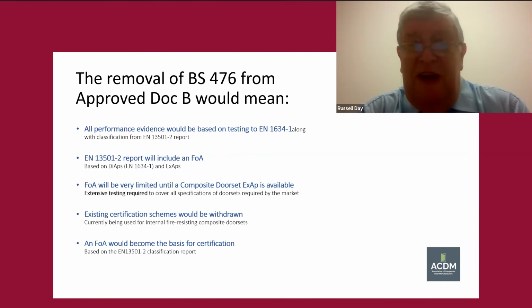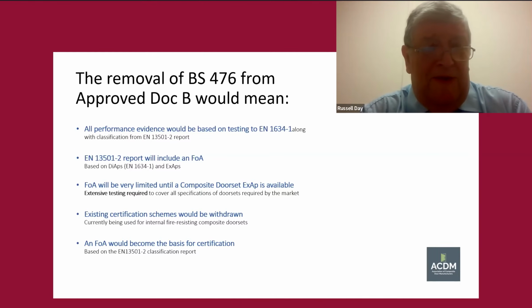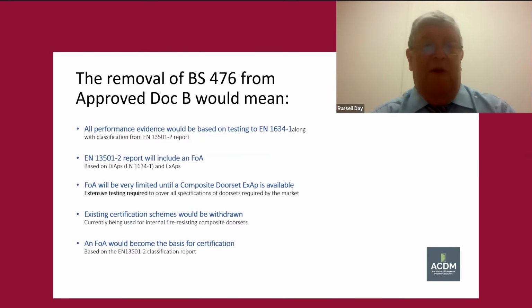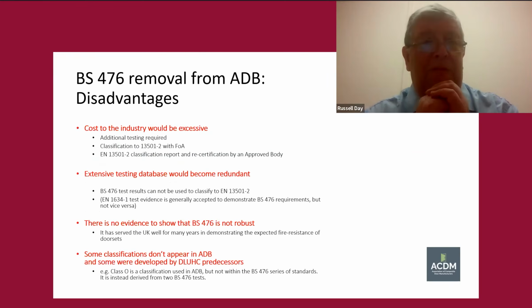Existing certification schemes, as I said, would be withdrawn because we can't have two fields of application, one based on 13501 Part 2 and one as a 476 based certification scheme. A field of application would become the basis of that certification based on the 13501 Part 2 classification report.